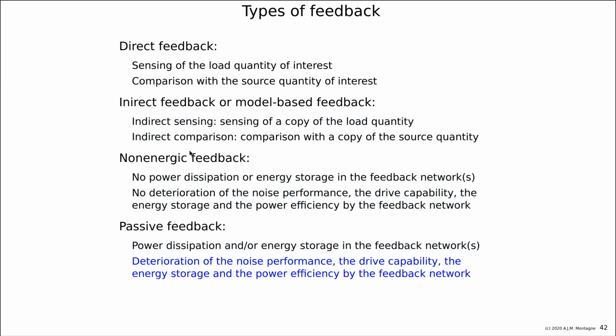So non-energetic feedback has better potential than passive feedback. Unfortunately, non-energetic feedback elements are only short and open circuit, transformers, and gyrators. So you can build a limited number of functions because for the gyrator there is no physical implementation. The transformer is not always very practical, or it is large and expensive.